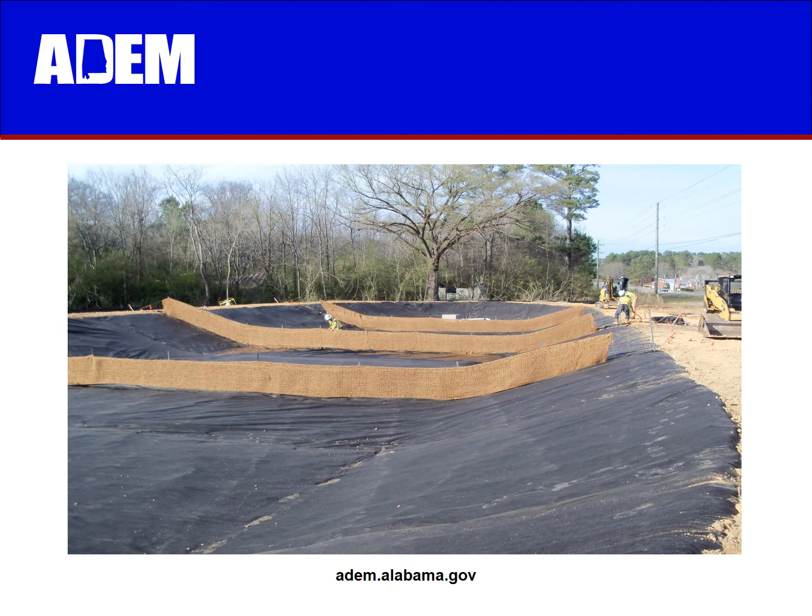And speaking of sediment basins, the proper installation of baffles and skimmers in the sediment basin allows more time for soil and other solids to settle out, resulting in higher quality of your stormwater discharge.